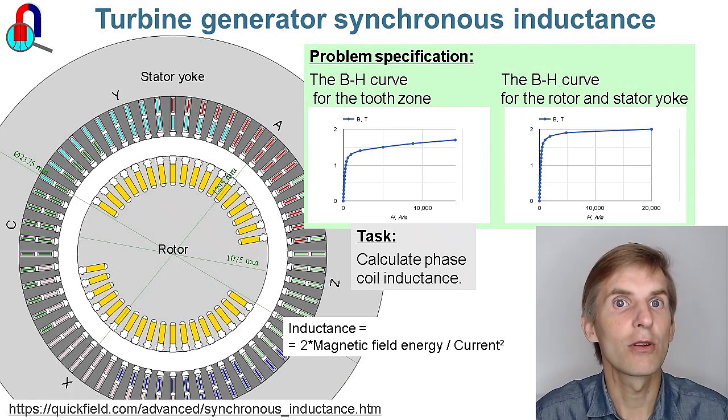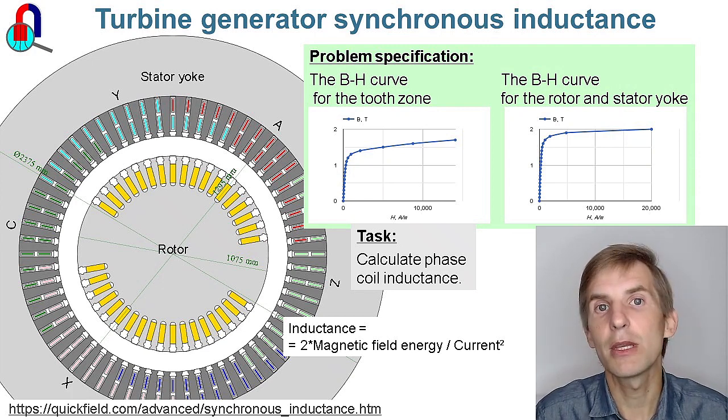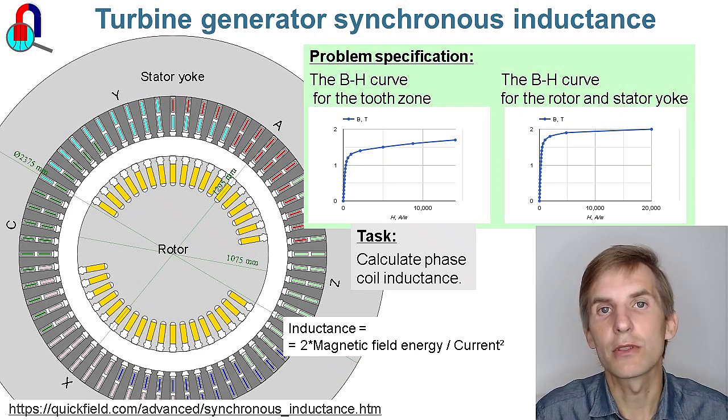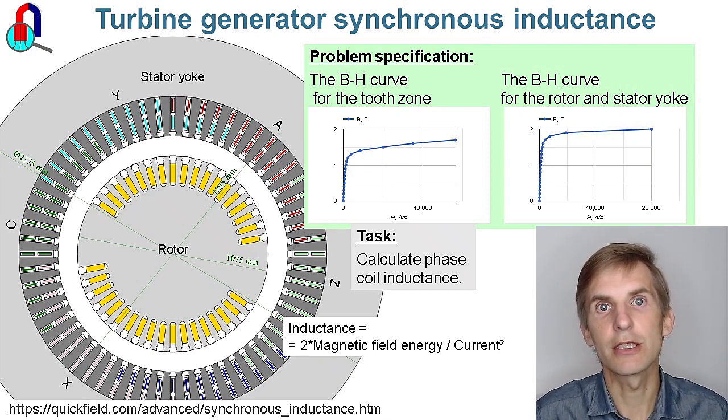My task is to calculate the maximum and the minimum inductance values. I am going to repeat the real case experiment. I will energize only the single phase, for example AX. I will put the rotor in different positions and calculate the inductance.